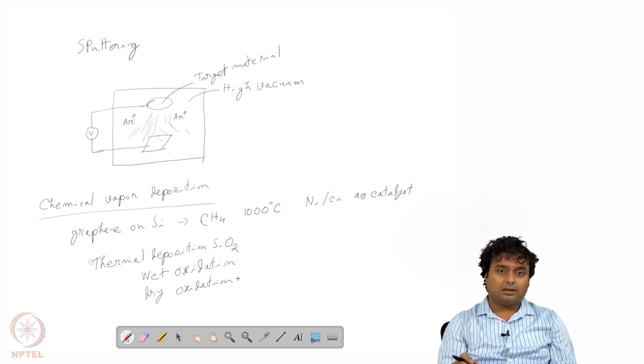In that case the oxide quality will not be so good, like the surface roughness etc., but the growth rate will be very high, right. So we can deposit that 900 nanometers of oxide in very small time. Then the rest, 90 nanometers or 50 nanometers, whatever we choose, we can again deposit by dry oxidation. So in that case the top surface will be made by dry oxide.